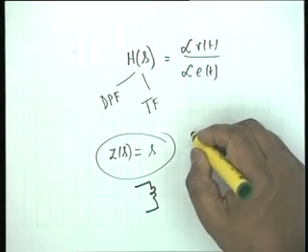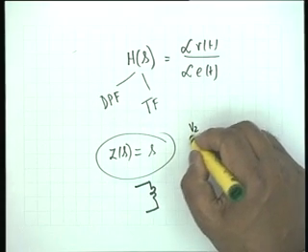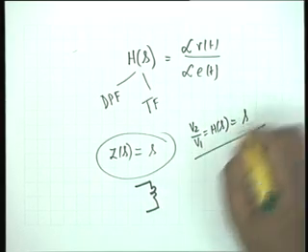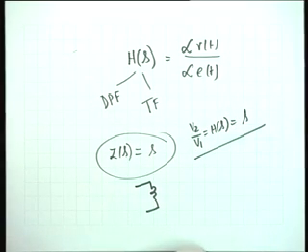But suppose it is a transfer function. Suppose it is V2 by V1 equal to H of S equal to S. Is this realizable? Why not? It is an unstable function. So one of the criteria for realizability is that the given function must be stable.